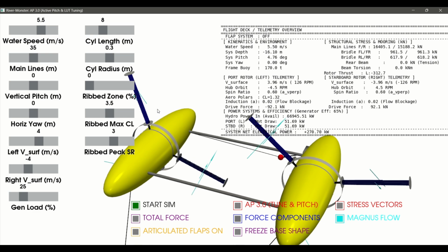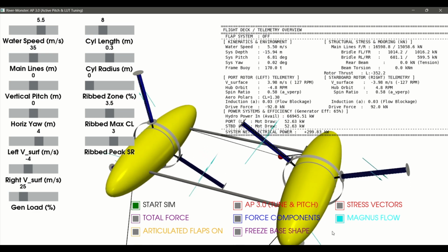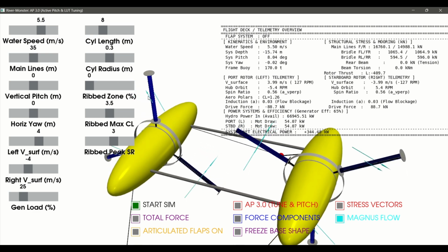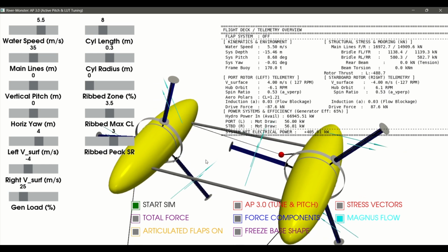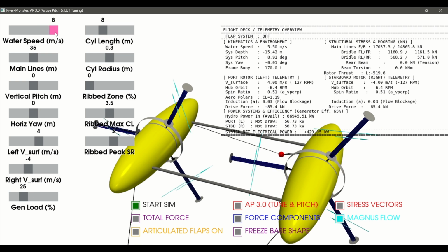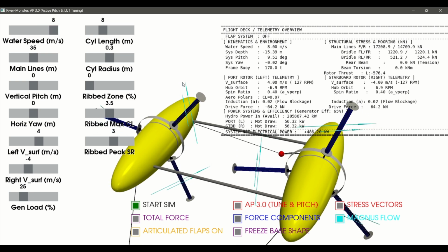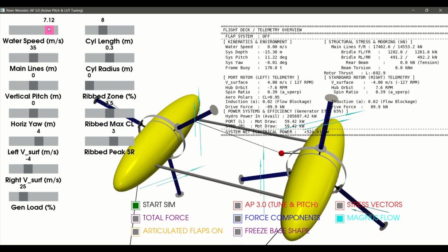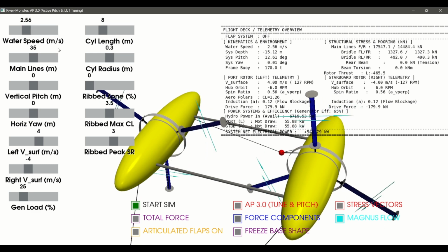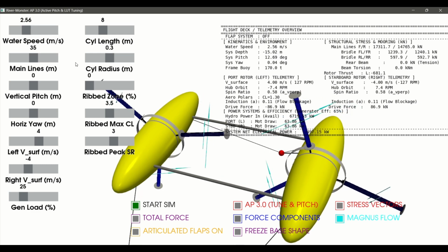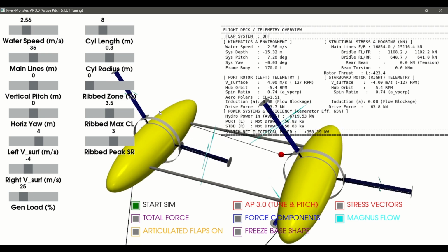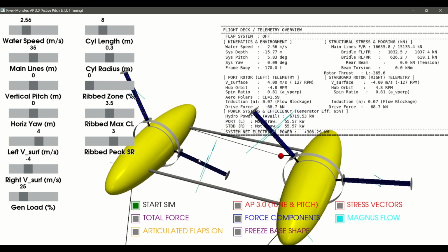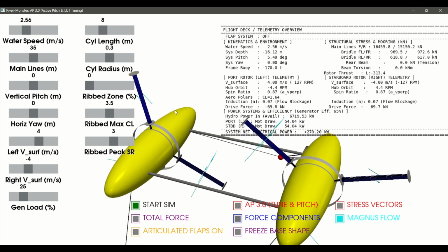Activating the flow vectors. These light blue lines illustrate how the water symmetrically flows around the rotor. But as we increase the cylinder's rotational speed, observe the shift. The fluid flow is violently deflected downwards. This is the Magnus effect in action. Surface friction entrains the fluid, creating a massive pressure differential between the upper and lower surfaces.